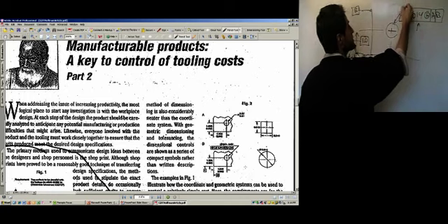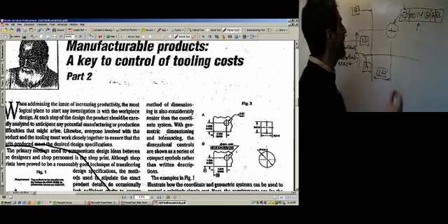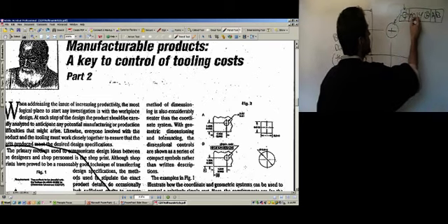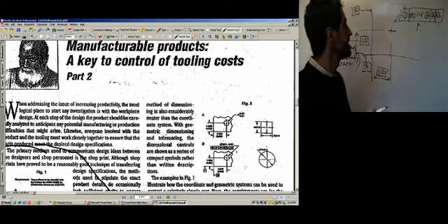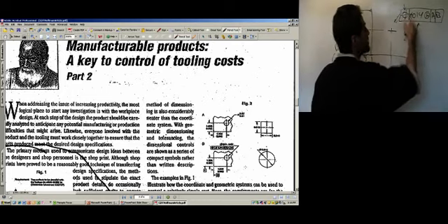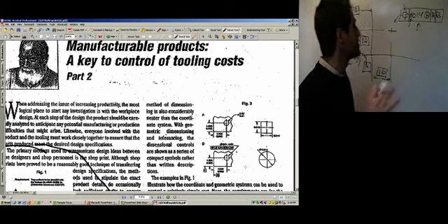That's a true position, or position tolerance, right there. And it says that there's a zone. Again, we'll represent that circle just by its center axis. It says there's a cylindrical zone, because remember, the diameter symbol says it's a cylindrical zone.